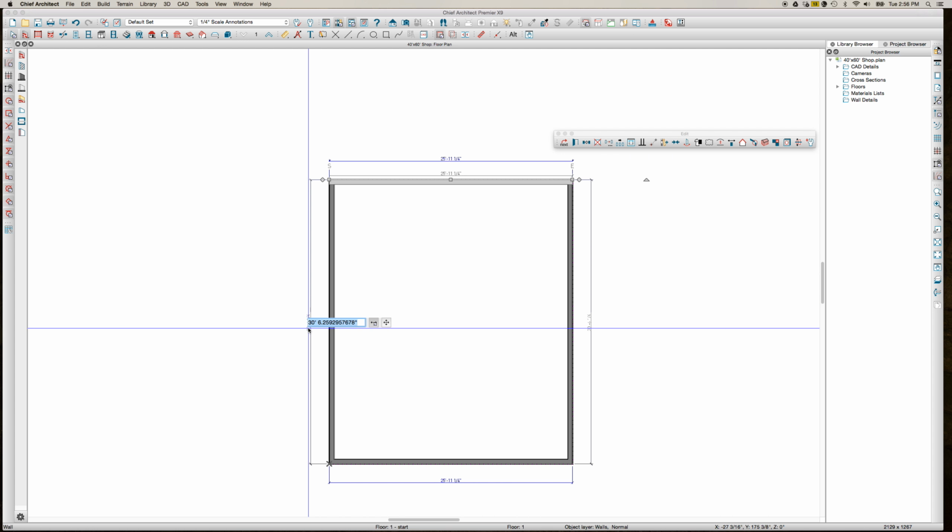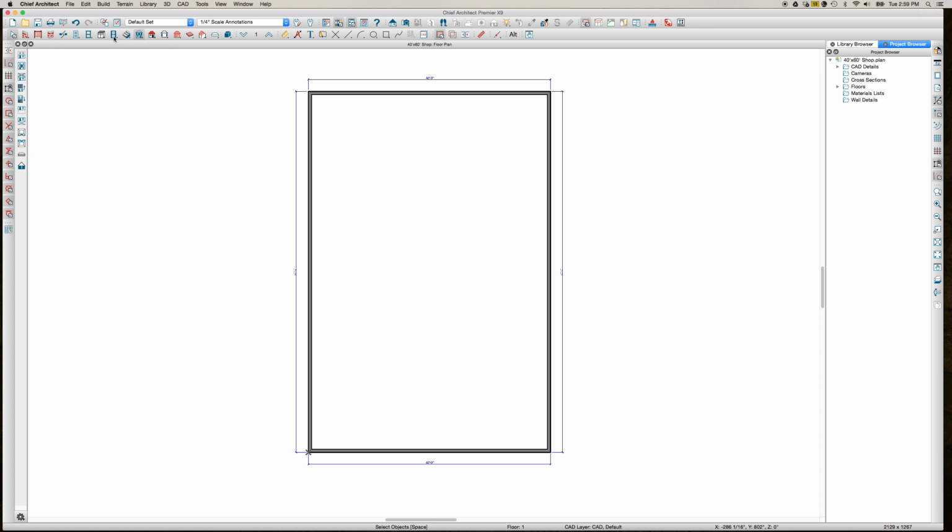We'll go back to the upper floor here. Now this project has 3 overhead doors in it. So we just drag and drop. And let's change the size of this door. The customer is looking for 12 by 10 overhead doors. So we'll go 144 and 120. I may change the door style later, but for now this will get us started.